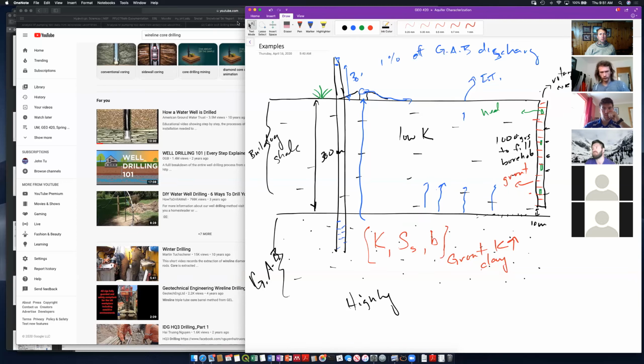I got a question about screened wells. So is the bottom of the casing still open to the wellbore? It totally depends. They're not always. Sometimes they're sealed, and sometimes they're not. Usually they're sealed. What usually, like for a water supply well, what you end up doing is there may be 3 or 4 sections that supplied enough water. So you might screen in 3 or 4 places, and then the bottom of the hole will still be closed.